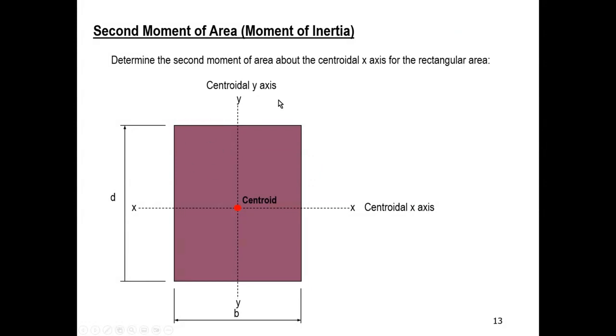Let's start with the centroid and the moment of area. When we say moment of area, it doesn't mean anything by itself. The second moment of area has to be defined with respect to a coordinate axis. I mean, you can calculate I with respect to the x, or you can calculate I with respect to the x prime. X prime is passing through the bottom, x is passing through the center. So which one are you looking for? So this one is I bar through the x. You could have calculated this one with respect to another axis parallel to that.